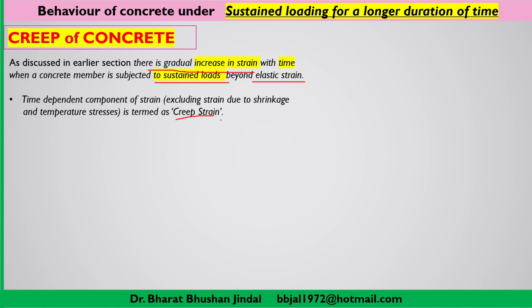Component of strain means, if you just recall the stress strain graph, in that graph the initial part was a straight line. That means it was a linear relation. So that linear relation gives us the information about the elastic behavior of the concrete, and the corresponding strain in the elastic range is known as elastic strain. And beyond that, behavior of the concrete will not be elastic, it will be inelastic type of behavior.